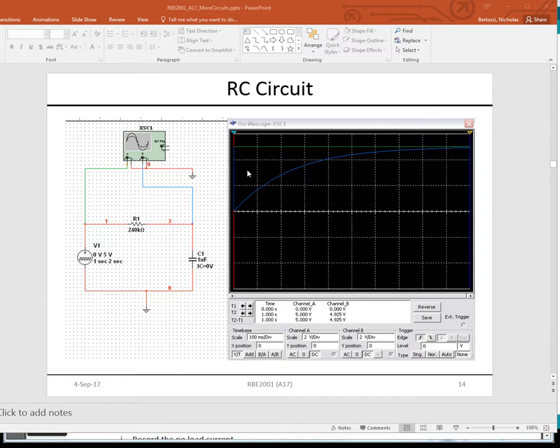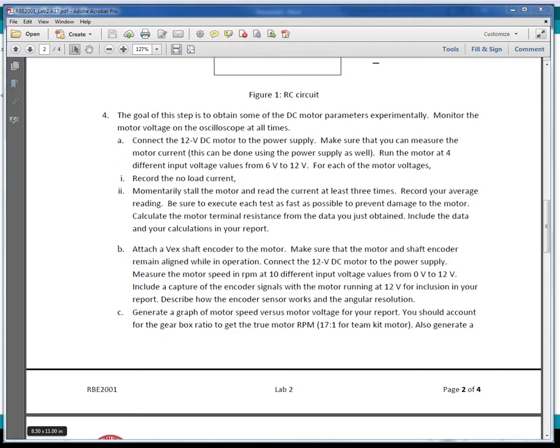So you can see that's what happens here, right? This is down at 0 volts. Suddenly the square wave goes up, and the charge has to build up until the voltage gradually increases over the capacitor. So that's what you'll be able to see here on the oscilloscope. As the voltage goes on and off, you'll be able to see what kind of waveform you get.